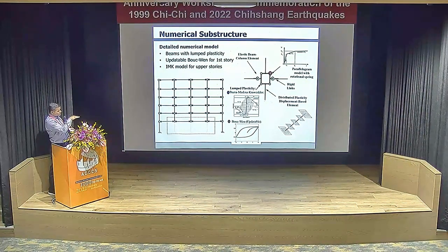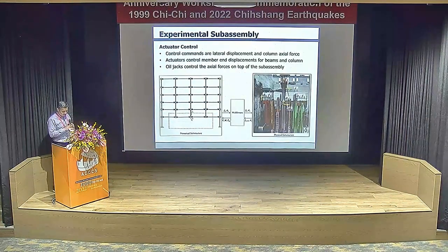We only chose the lower stories because we're going to measure a beam hinge in the experiment, and especially all the hinges in the lower story are going to go through a similar loading pattern. We could have probably done it for the upper stories, but they're probably going to experience a slightly different loading pattern. So we only updated the hinges for the numerical model on the beam in the lower stories, and I'll have a more detailed slide on that a little bit later.